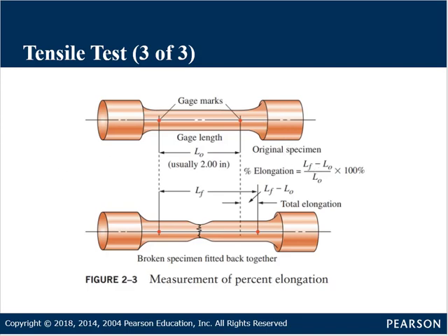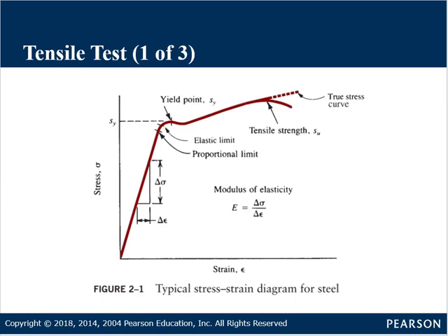When I said this tensile test was typical of a ductile part, what you're seeing is lots of deformation before the thing finally fails up in here. So a ductile part will go through a lot of deformation before it finally fails. The opposite of ductility would be brittleness, and a brittle part would tend to fail before it starts to deform very much at all.